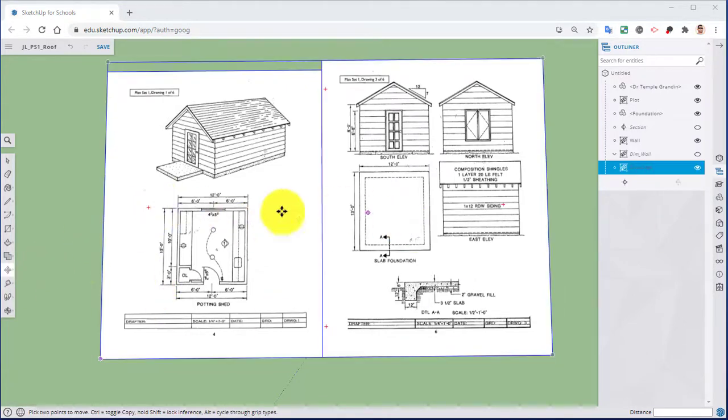So these are the two drawings from the Harley plan set or Harley Blueprint series. This is plan set 1. So this is drawing 1, and this is drawing 3. This is showing the elevations, the south, north, and east elevations, and this is the isometric drawing of how the exterior looks. So as you can see, our roof has a 7/12 pitch. That means for every 12 feet linear or out the roof goes, it's going to go up 7 feet.